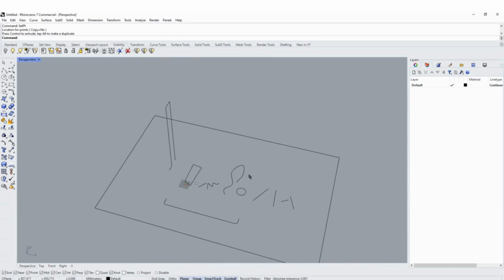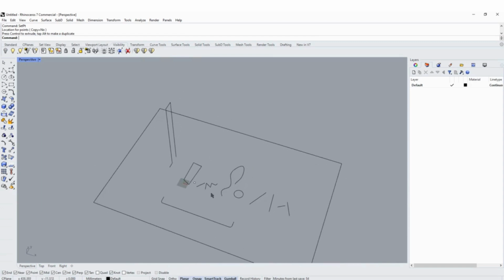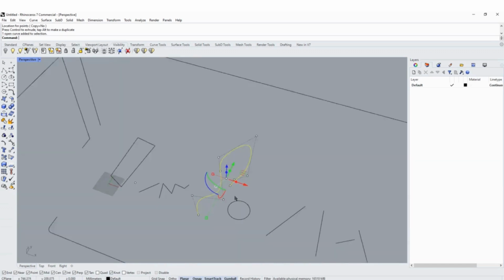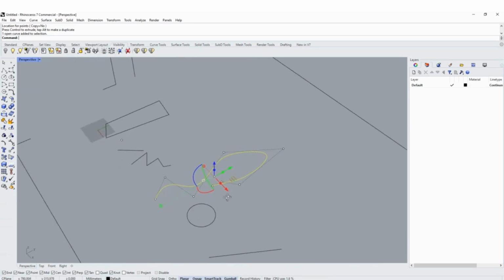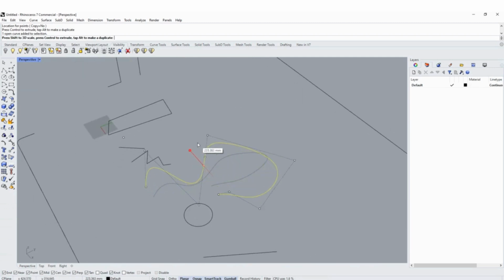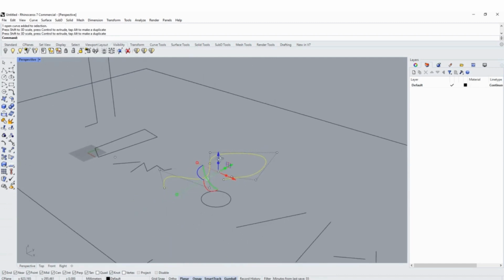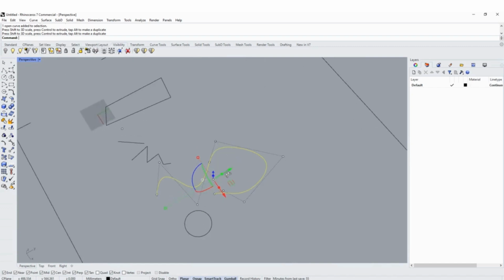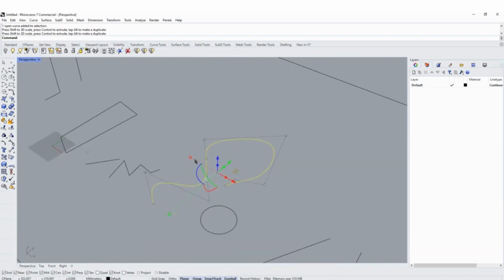And then another function, another command that, of course, we lightly touched with a gumball is the scale. So let's say I select this one, I see my beautiful colorful gumball over here. I can scale elements either to this dimension, but then there is another choice that you can also go and just simply type scale. There are 3 ways to scale. For example, maybe you see that already here, I can only scale into 1 dimension. So this is only scaling here.